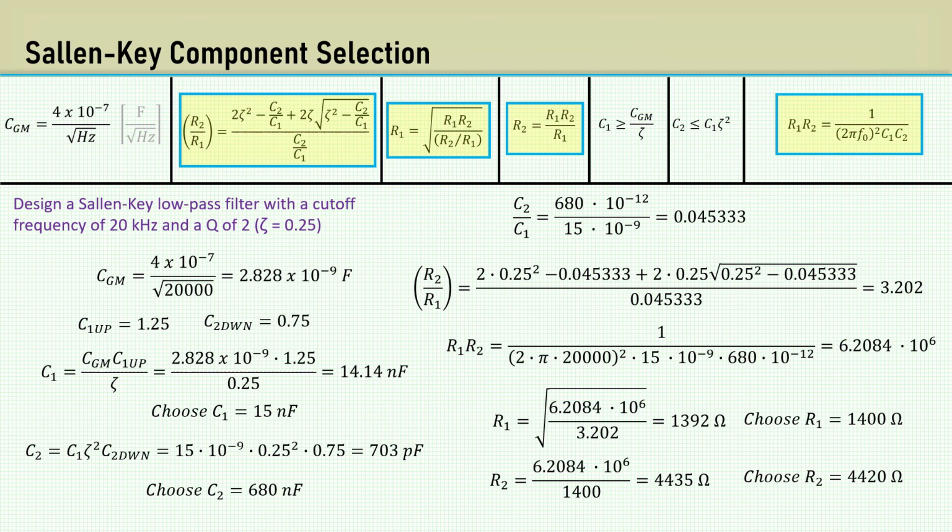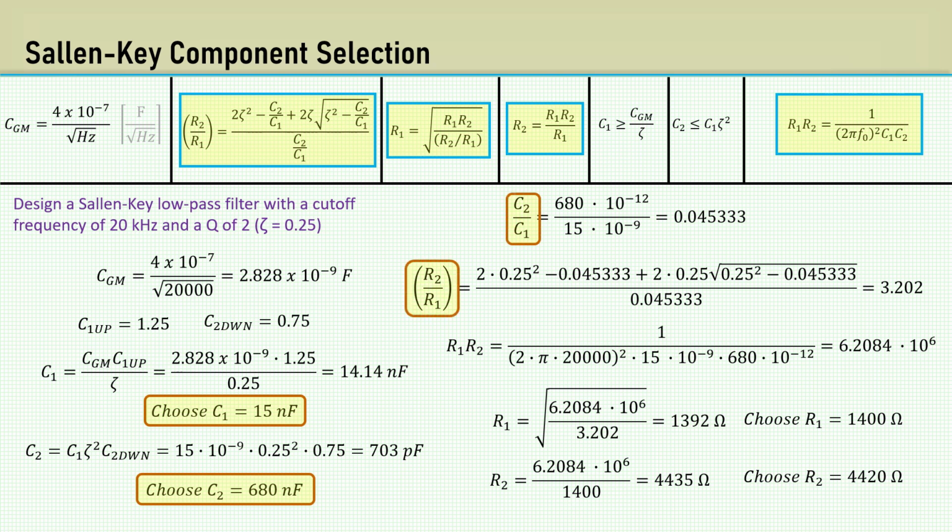In the last video, we derived some equations to calculate component values for the Sallen-Key low-pass filter. It was a method using the geometric mean of a capacitance value, then having both capacitors set to standard values right off the bat. The ratio of C2 to C1 was then used to determine the ratio of R2 to R1, and standard values are chosen from the results. The spreadsheet we are developing will do all these calculations with ease.